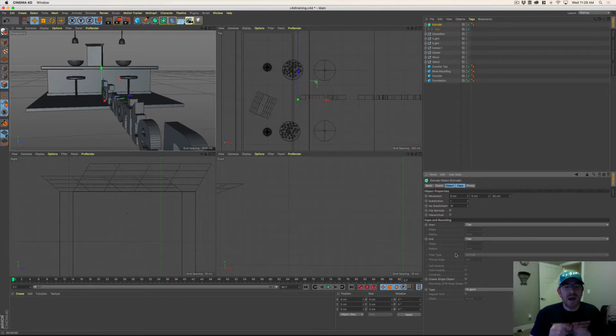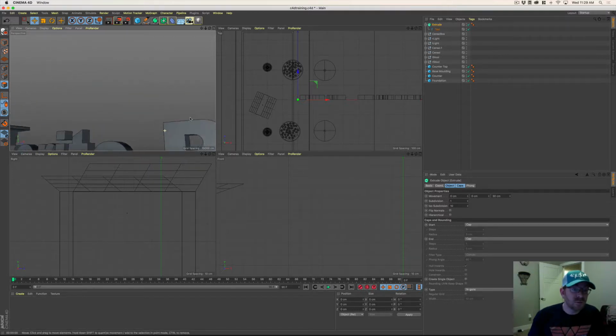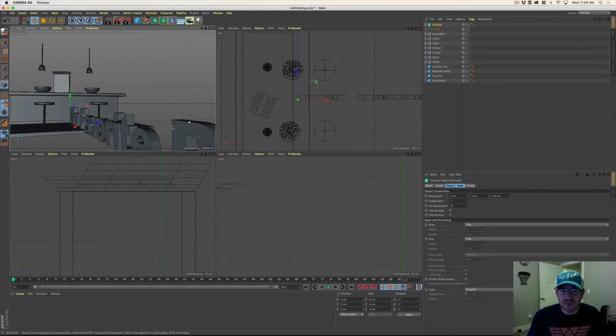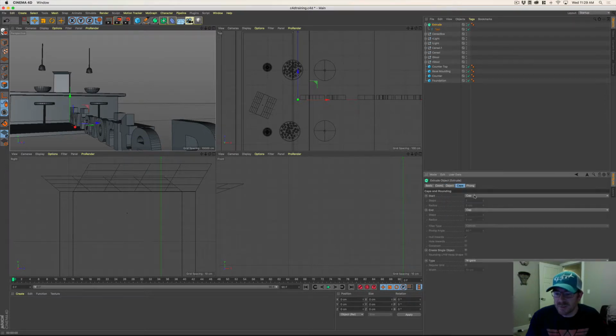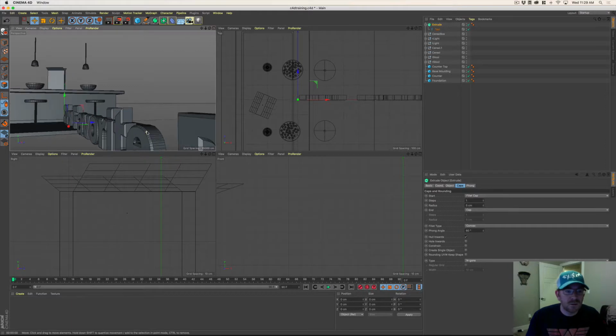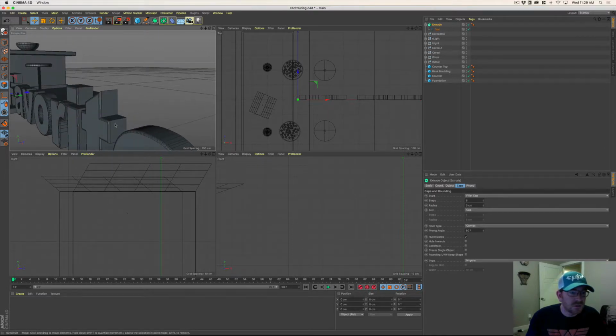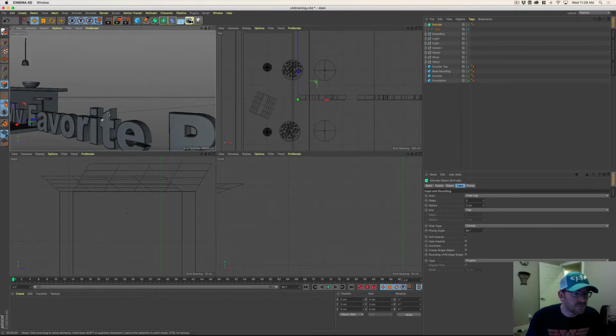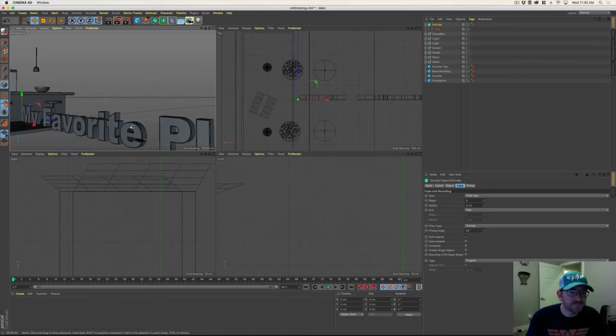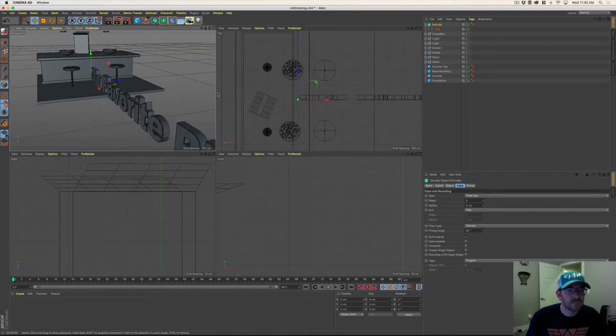I also want a cap on the front of it. The front of the words, I want a little bit of a round. The back of the words, I don't care because I'm going to show you that it doesn't matter for this particular case. So you can see there's a caps tab. Caps, fillet cap. I would like there to be more steps, let's say 5, and a radius of 3. Kind of keep things consistent. So it adds a little bevel to it. Okay,